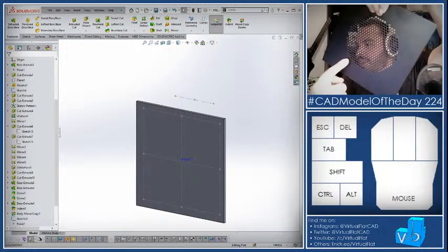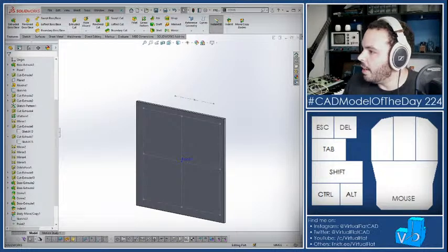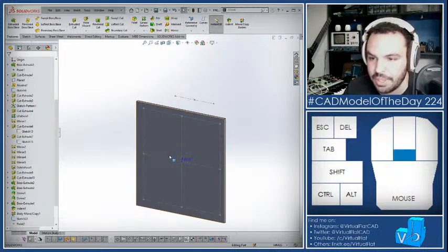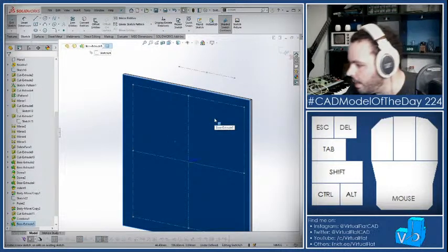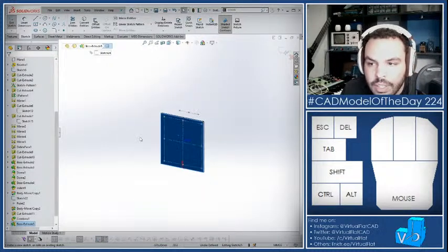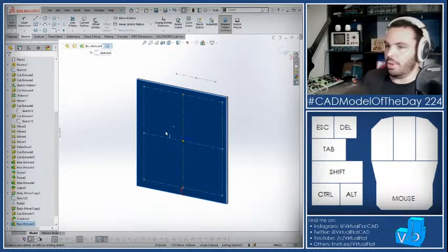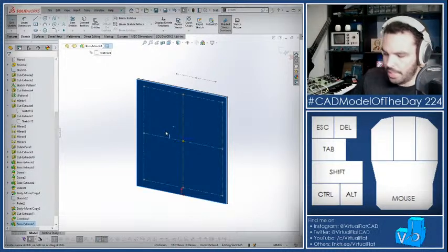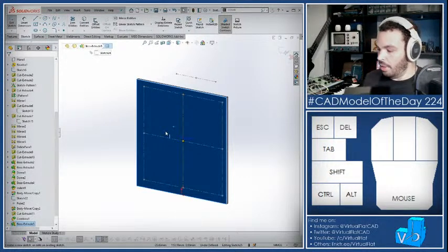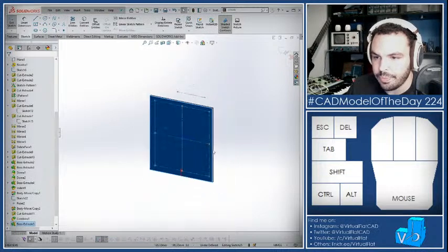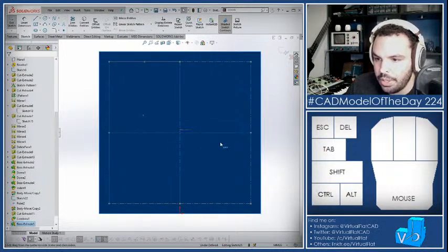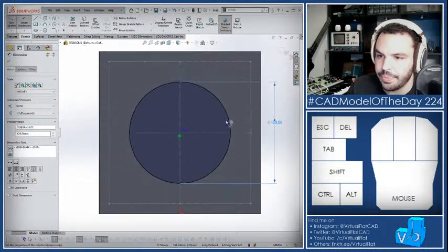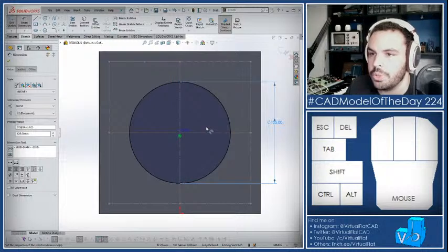So now I'm gonna try this speaker pattern. I definitely will not use sketch-driven pattern because I don't think anyone wants to see me place 100 holes. Instead, I will use fill pattern. So what I'm gonna do is approximate how large that circle is, and there are ribs on the inside that are pretty close. So again, it's like 125. I guess I could reuse the other circle, but whatever. I already got the circle sketched up anyway. All right, so those are where all the speaker holes have to go.